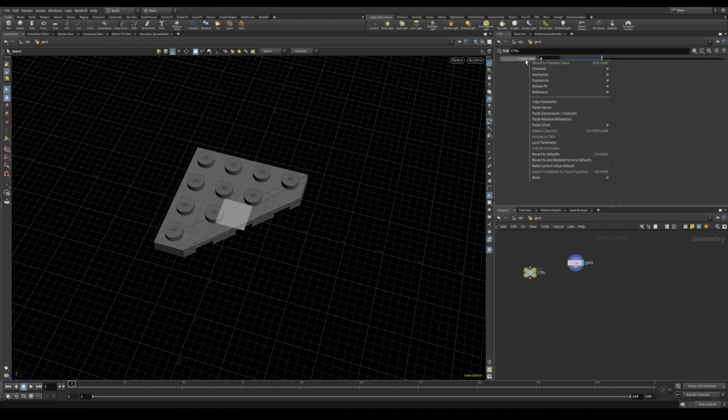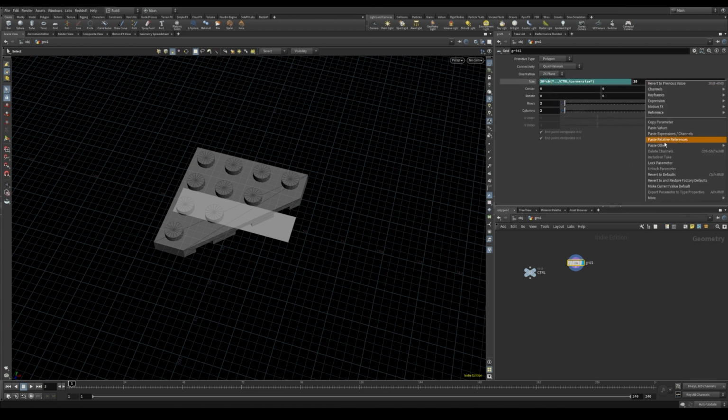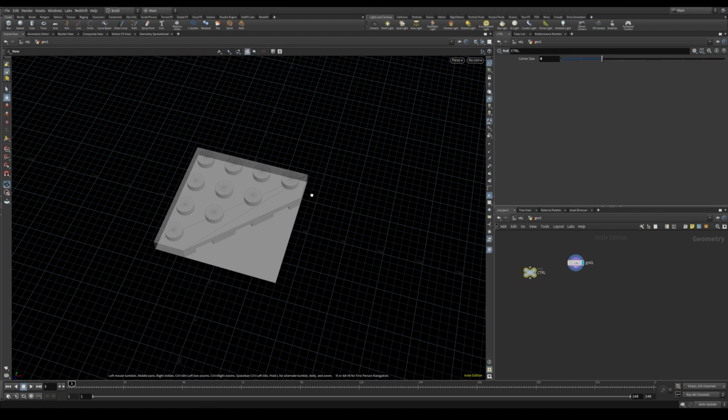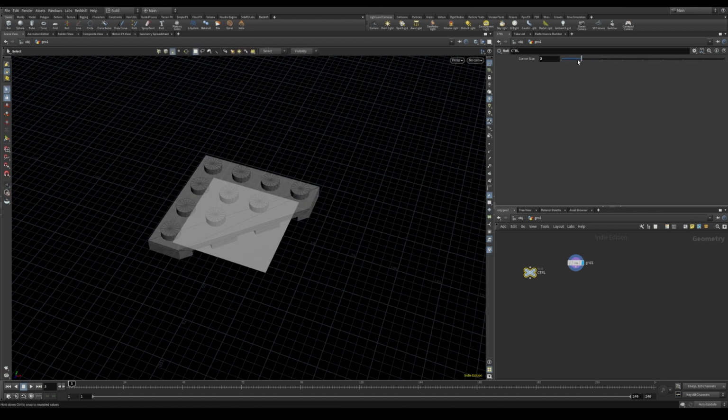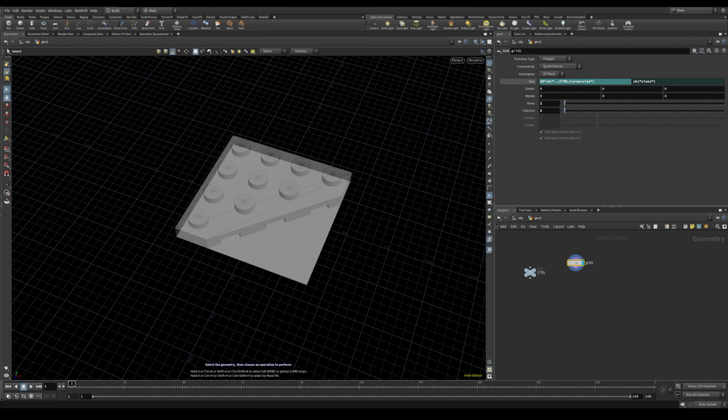So we can right click on the corner sides, copy the parameter, and here we can type multiply and paste the relative reference with right click. And here we can do the same, or you can even copy this parameter to this, because it will always be a square. So now we already have our controller working, because we are deciding the piece size with the slider. And so we can set it to the 4 as the current reference, and let's move on.